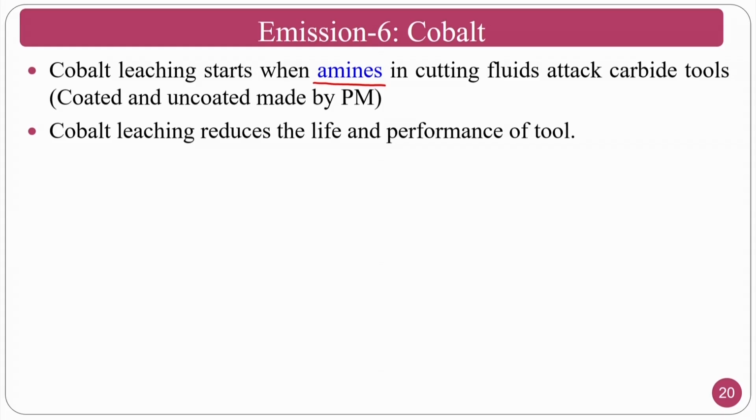Tungsten carbide or other powder metallurgical route tools have cobalt as a binder, with tungsten carbide or tantalum carbide. Tools are mostly manufactured by the powder metallurgy route, and if I want to generate some angles, you have to go for a tool and cutter grinder.